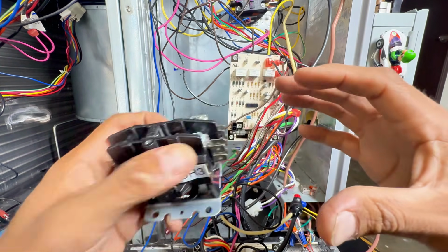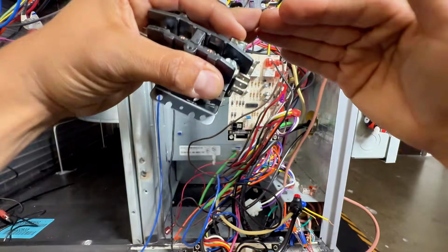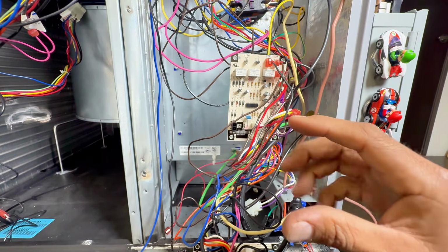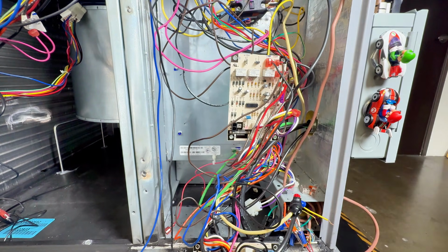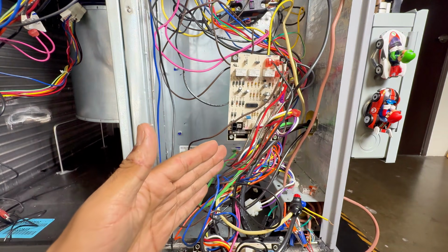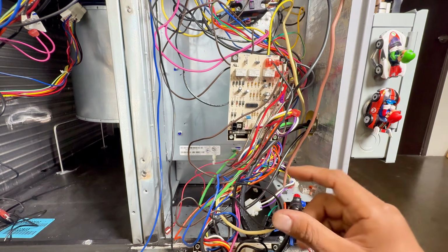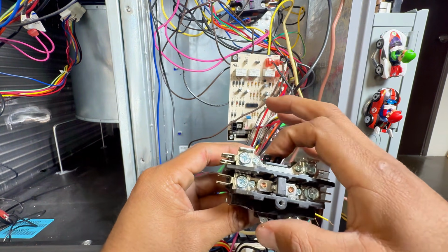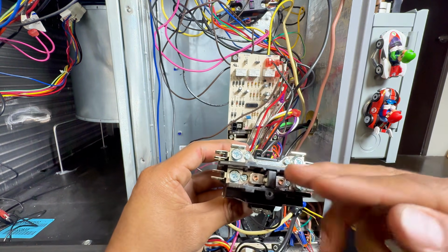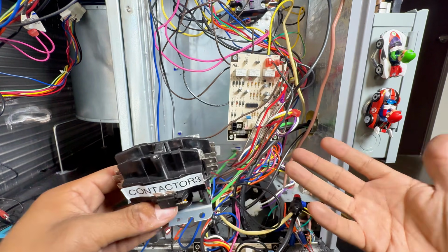We were able to see how on the ladder wiring diagram, you had your low voltage on the bottom, high voltage on top, separated by the transformer. But that's the idea behind really the air conditioning system, any schematics that you're working on, whether it's connection or ladder wiring diagram, you're using low voltage, 24 volts, to then send the high voltage through that bridge